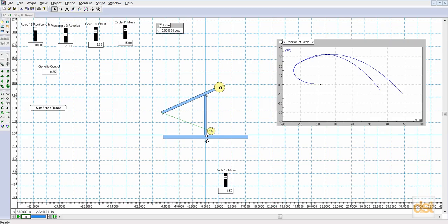The criteria we'll use for stopping the simulation will be based on two things. One will say when time is greater than 0. The other will be when the payload position is less than 0. We know that when the trebuchet swings, the payload is always going to be in the positive Y region. Only when it lands out here is it going to cross and go into the negative region. And that will be some point after time equals 0.